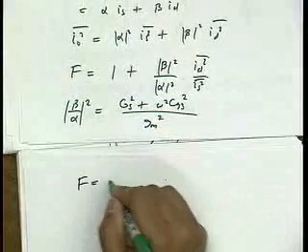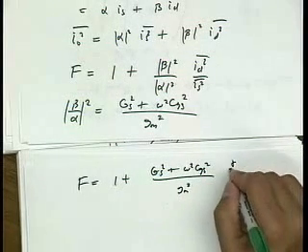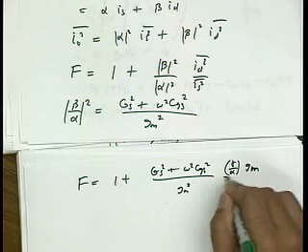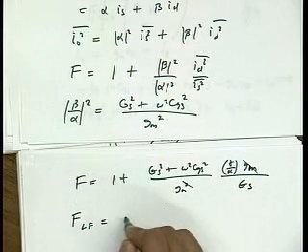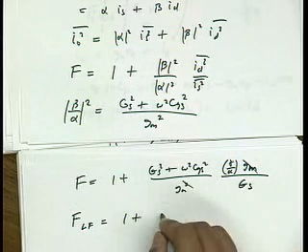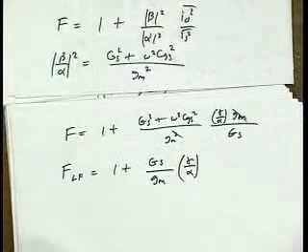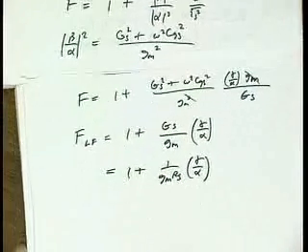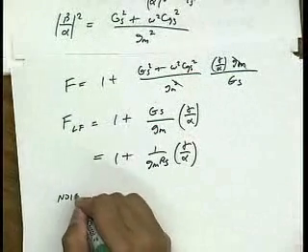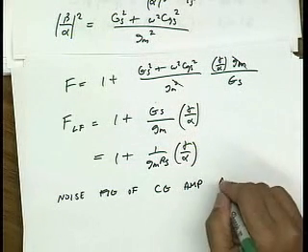So if I come back here, I have F is 1 plus (GS squared plus omega squared CGS squared) over gm squared, times I drain, which is gamma over alpha gm, and this is GS. You can see this cancels here. And at low frequencies, I get 1 plus, this GS cancels out with that one, GS over gm, gamma over alpha, or 1 plus 1 over gm RS, gamma over alpha. So this is the noise figure of a common gate amplifier at low frequencies.